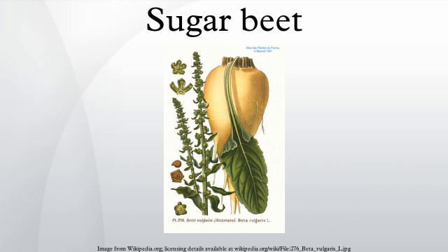Carbonatation. Carbonatation is a procedure which removes impurities from raw juice before it undergoes crystallization. First, the juice is mixed with hot milk of lime. This treatment precipitates a number of impurities, including multivalent anions such as sulfate, phosphate, citrate and oxalate, which precipitate as their calcium salts, and large organic molecules such as proteins, saponins and pectins, which aggregate in the presence of multivalent cations. In addition, the alkaline conditions convert the simple sugars, glucose and fructose, along with the amino acid glutamine, to chemically stable carboxylic acids. Left untreated, these sugars and amines would eventually frustrate crystallization of the sucrose.